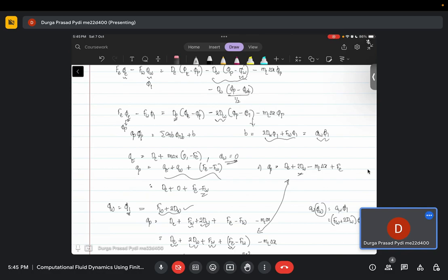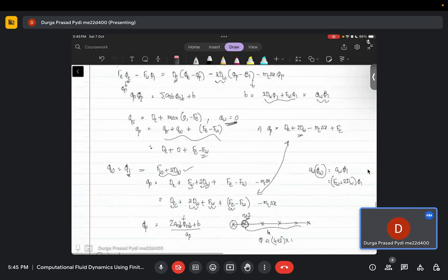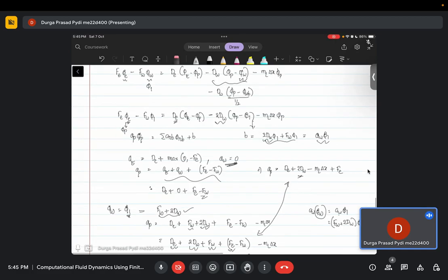So you don't have to make this equal to 0. The only thing you have to take care of is not getting confused with this half term that is coming in. If you just write dW, then the half cell that you are considering at the boundary will be gone. So whenever you have a Dirichlet condition, instead of dW, it will be 2dW. That will be the only difference. You don't have to update your B term. That gets automatically included in your Gauss-Seidel loop.